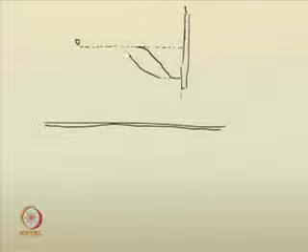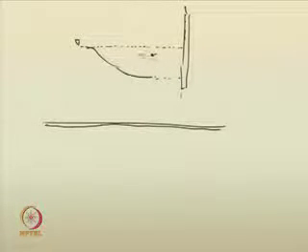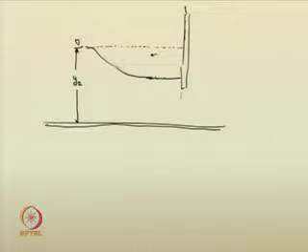After a few seconds, this negative surge reached here, and like that it goes on, right. This is how the propagation of surge occurs. So, just take a negative surge in such a way that the upstream end has the same depth as before the raising of the gate.